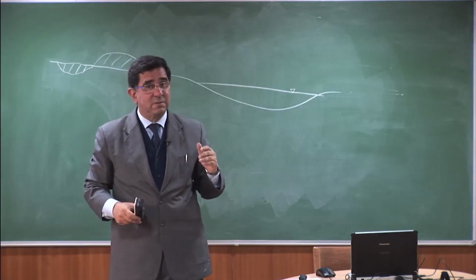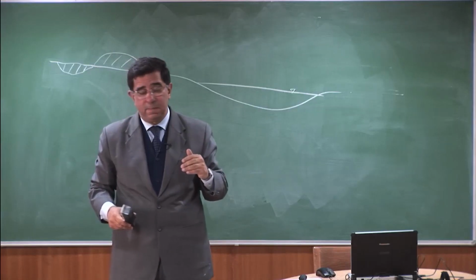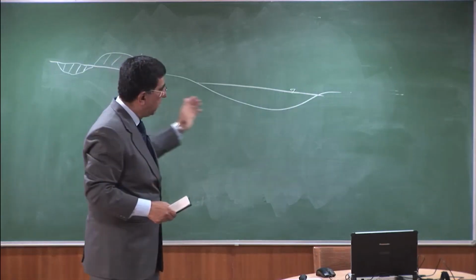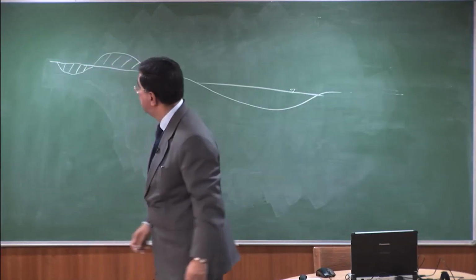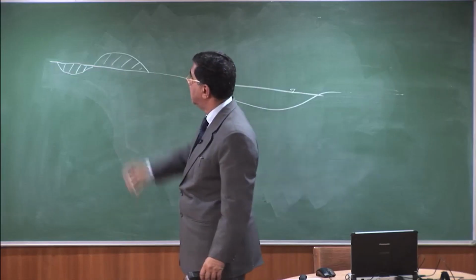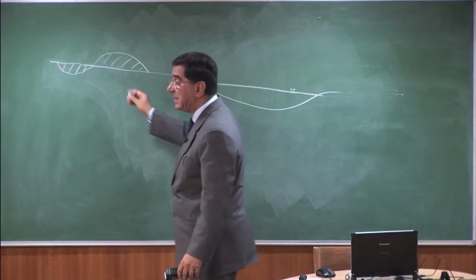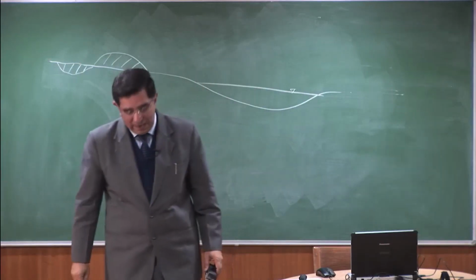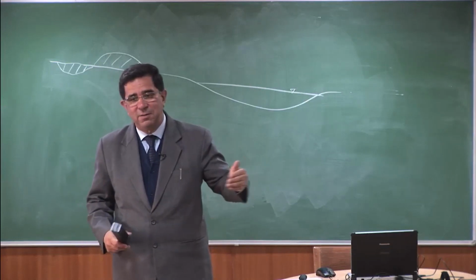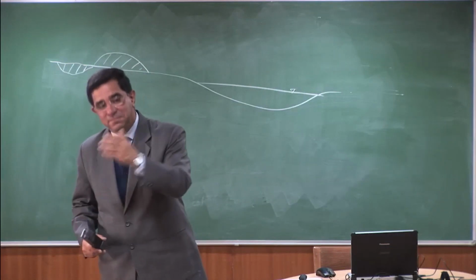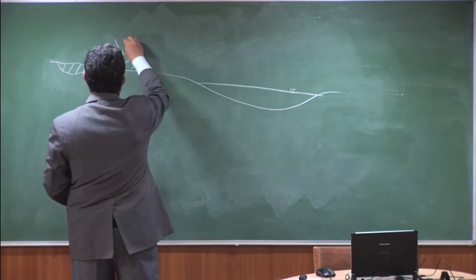and will you get surface contamination, or will you get groundwater contamination here? What kind of contamination do you suspect? I think I've gone outside the limit, but nevertheless. If this is clay, if the soil is clay, what will happen? When the rain comes, will the water go into the soil or will it travel along the slope of the ground? Right. So if it is clay, then